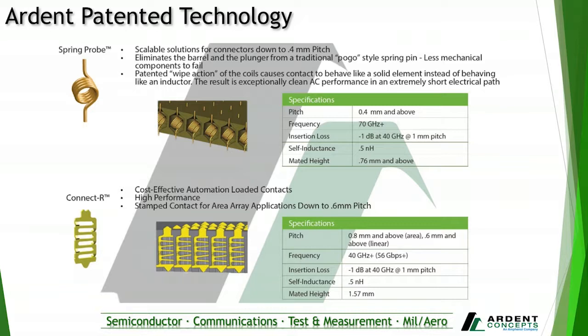As you can see here, the RC spring probe acts similar to a compression spring in that when axial force is applied to the straight portions of the wire form, the coil in the center compresses, similar to that of a solid state compression spring. And in addition to compressing the coils together, that unique angled feature that you can see allows the coils to wipe against each other. This wiping motion can also aid in reducing oxidation and debris.